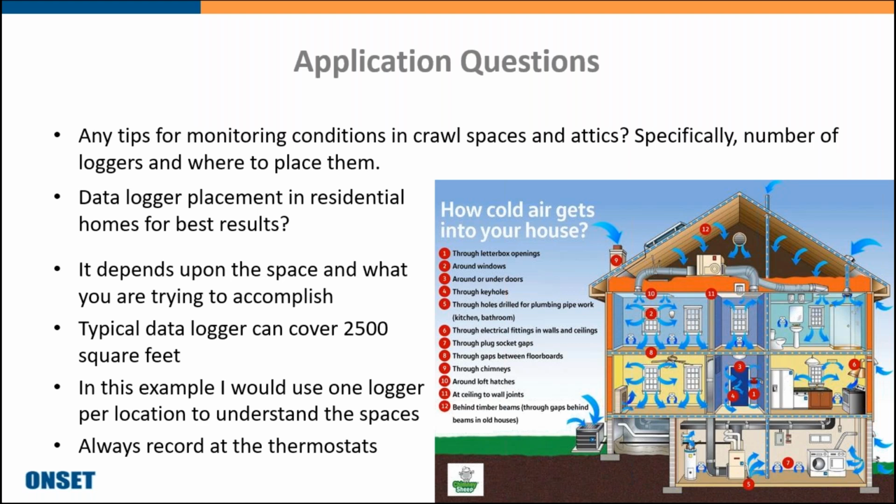For some placement methods, we always recommend placing the data logger right at the thermostat, especially if you're trying to verify the operations of your HVAC system. Placing it at the thermostat, obviously, that's what's going to be triggering your heating or cooling system to kick on. So that's the best place to take the measurement.